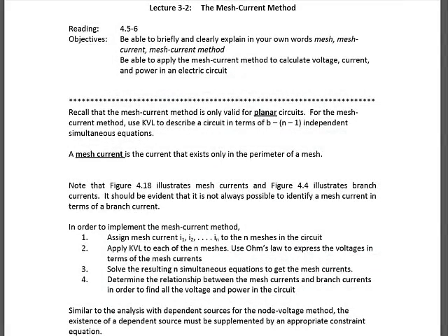Today's lecture will be an introduction to the mesh current method. The mesh current method is a systematic application of Kirchhoff's voltage law. Recall that the mesh current method is only valid for planar circuits. A planar circuit is one that can be drawn such that none of the branches are overlapping.